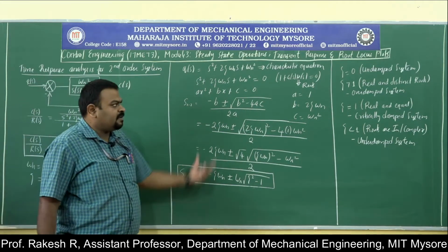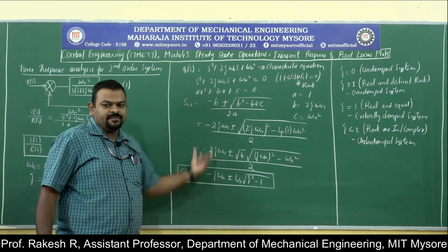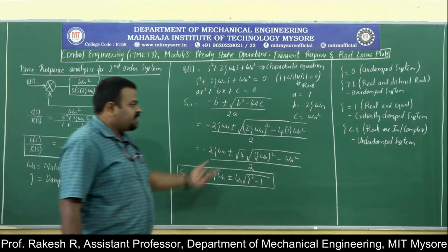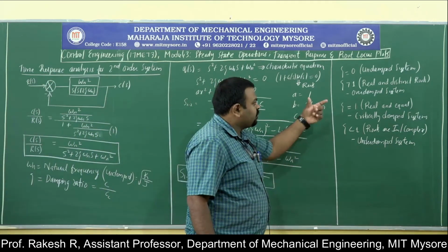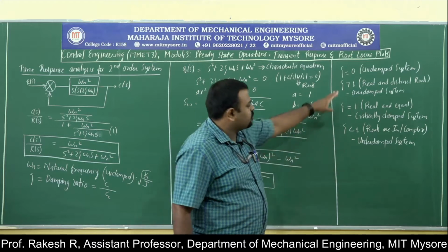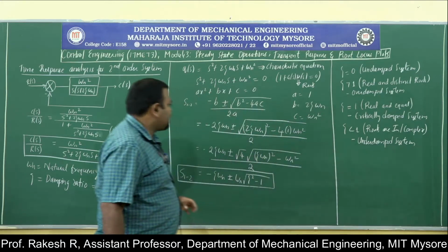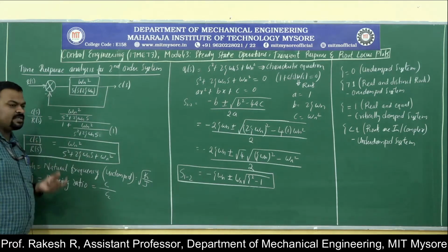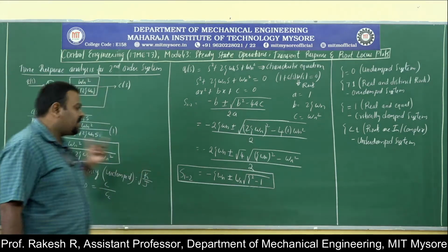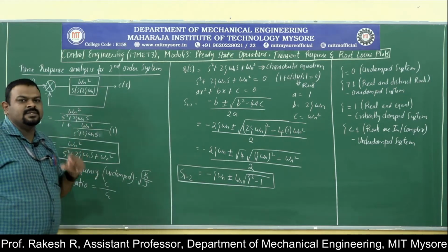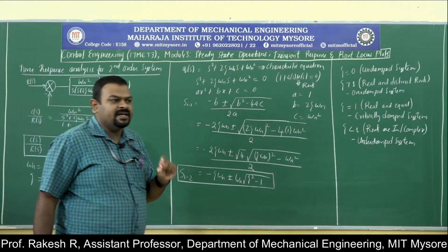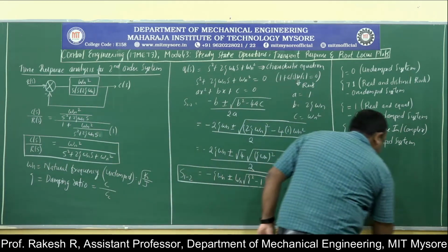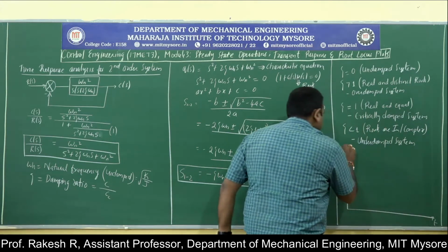So these are the different equations we need to solve. If we solve the characteristic equation, we will get different roots. The roots of the characteristic equation will be the solution for this. After this, based on the roots of the characteristic equation, we will substitute the values here. We will calculate what is C of S. Again, based on the input R of S, C of S is converted into C of t by inverse Laplace transformation. So if I plot all those things, t versus c,